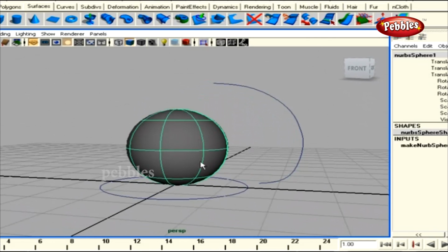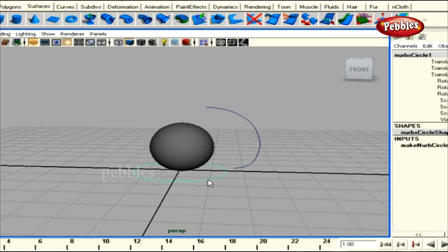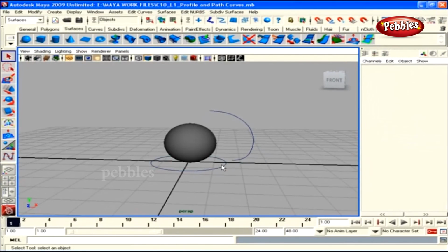Thus, whatever surface we are to create from curves, we're going to create them either from a path curve or from a profile curve. Now, if you still have a problem understanding these types of curves, don't worry, you will as we move through this lesson. Now, we're going to extrude a curve. All right, what's that? Well, the command itself is termed Extrude, and what it does is extrude a profile curve into a surface. But we need the direction for an extrude. Yes, it's done with the help of a path curve. We'll move right ahead into the scene and finish her off.